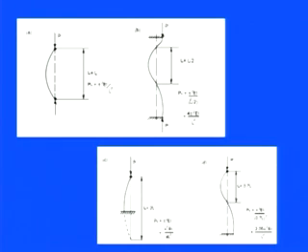So the equivalent length is always important to check the buckling part, how the buckling can happen, and what kind of sine waves come under the load actions. So we simply compared all those four situations based on the load application and the effective length, to check it based on the Euler theory.